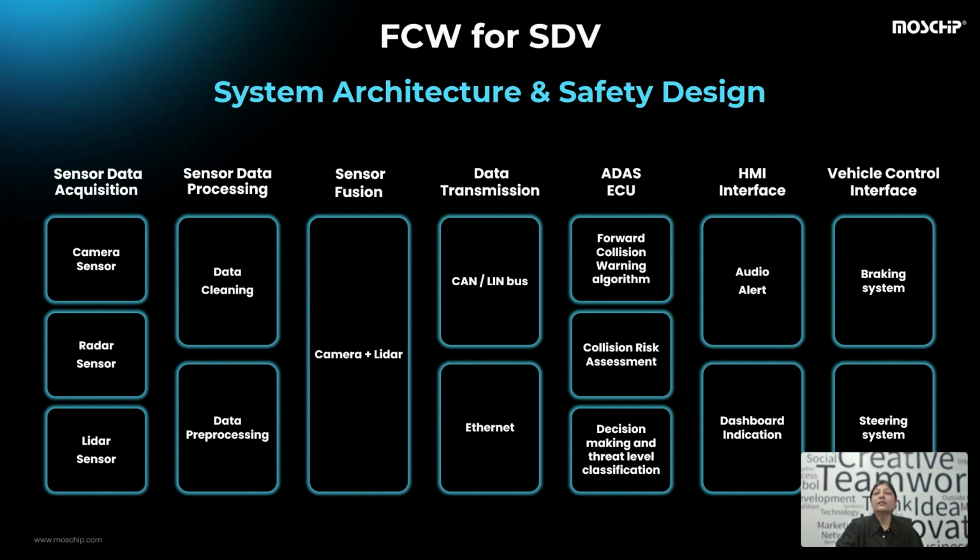So we stack other defenses on top. End-to-end communication protection is used to detect corrupted, lost, and delayed messages through cyclic redundancy checks, sequence counters, timeout detection, and message authentication. Functional monitoring tracks the health of the software and hardware at runtime through watchdogs, runtime checks, and built-in self-test.